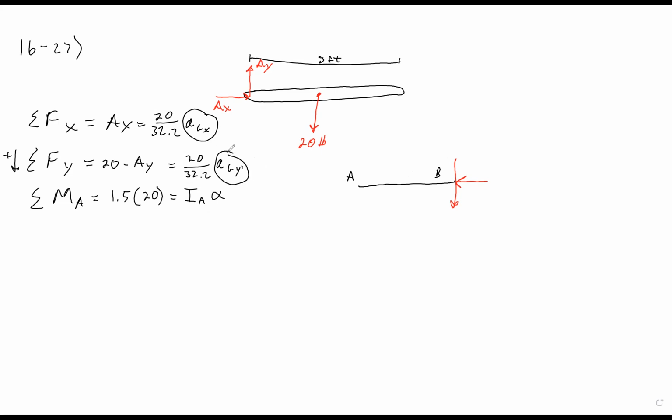All right, but where is acceleration AGX and AGY? Actually, it's in the middle of the rod. So my diagram isn't exactly appropriate for finding extra terms that I already have in my first 3 equations. What I want to do is erase, label this G, and my relative acceleration diagram will only go to G.